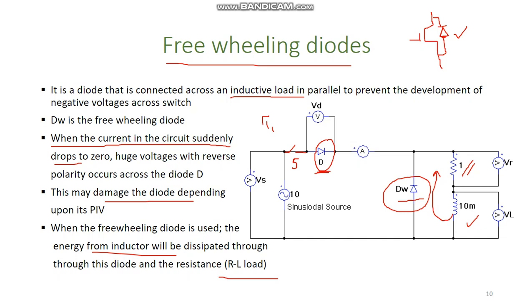The reason is the same: these diodes are also freewheeling diodes. Since we do not know what kind of load we are dealing with, for example, if we are dealing with an inductive load, in that case these diodes are necessary across these switches in order to protect them from the high voltages that will appear across the switch due to an inductive load.